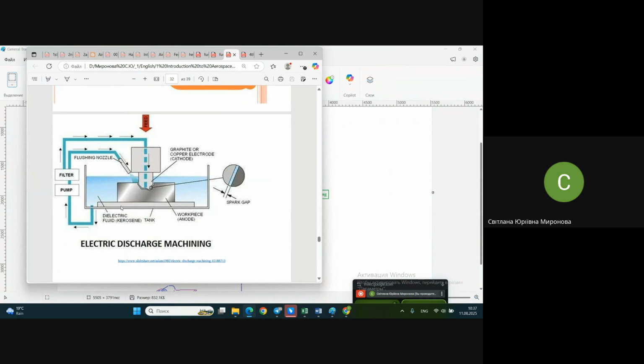Material may be hard to machine, so-called hard-to-cut materials, and material may be fragile at the same moment. Fragile means that it will tear off pieces on the surface. Whole grains may be torn off from the surface. And finally, even if you have the necessary sizes, the surface roughness does not correspond to the demands of the one who demands you to produce it.